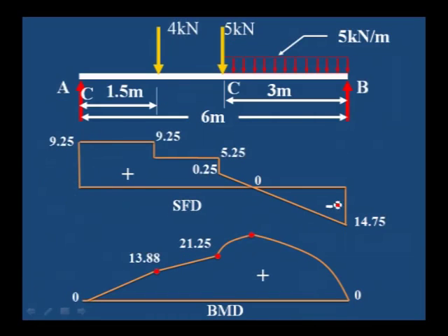This is the shear force diagram. What you can observe here, this is the RB value, shear force at B negative, shear force at A positive. There is a vertical drop at A, a vertical line at A as well as B, and then it is constant from C to D, and then you can observe here it is a drop.